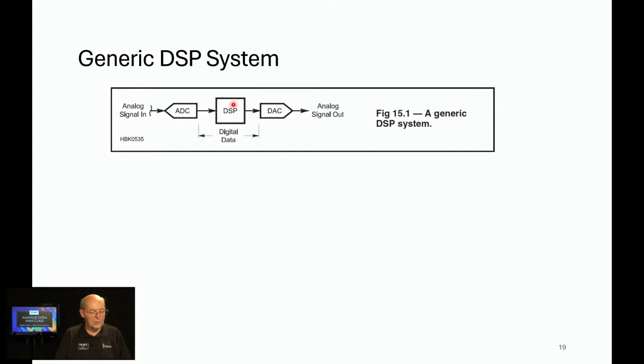And eventually, when we're done with that, let's say that we're demodulating single sideband, for example, we want to convert that back into something that we as humans can understand, and that's what the digital to analog converter does, analog signal out. So we can bring a signal in, do all kinds of magic on it, completely in software, all digitally, convert it back to audio, and then we can hear it. So this can happen any place in a radio.